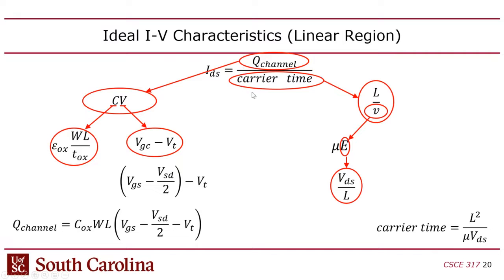So how would that work? Well, it used to be that you would save a little current. Well, you can also scale the voltage. Well, the point is that none of that is still in effect anyway. So this is why we have this issue of dark silicon, where you can't run all the transistors on the chip without exceeding the power envelope, because the amount of power used per unit area is actually increasing now as you scale down the transistor sizes.